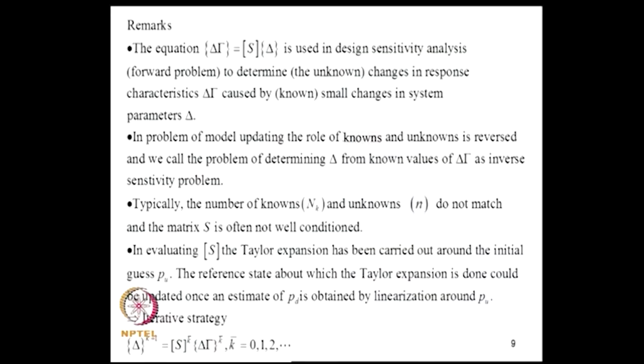If you consider this equation, that is delta gamma is equal to S into delta, and you are looking in this direction, that means given changes that are made to system parameters, I want to know what would be the change in response characteristics. This is a problem in design sensitivity analysis. For example, you may like to change the stiffness of some element in a structure and you want to know what would be the change in natural frequencies, and so on and so forth. So, this is a forward problem, and that is a design sensitivity problem.